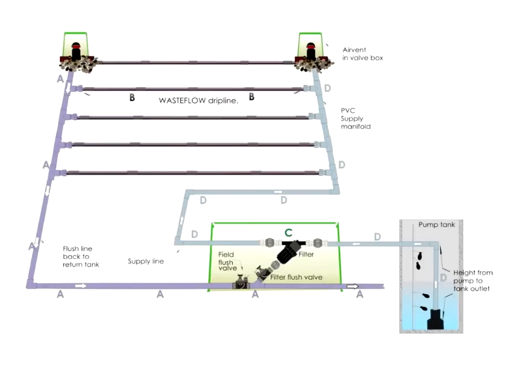Okay, now here we have a typical system. We have a pump tank, and I generally will recommend 4 floats: an emergency off, an activate, an alarm, and a super alarm.